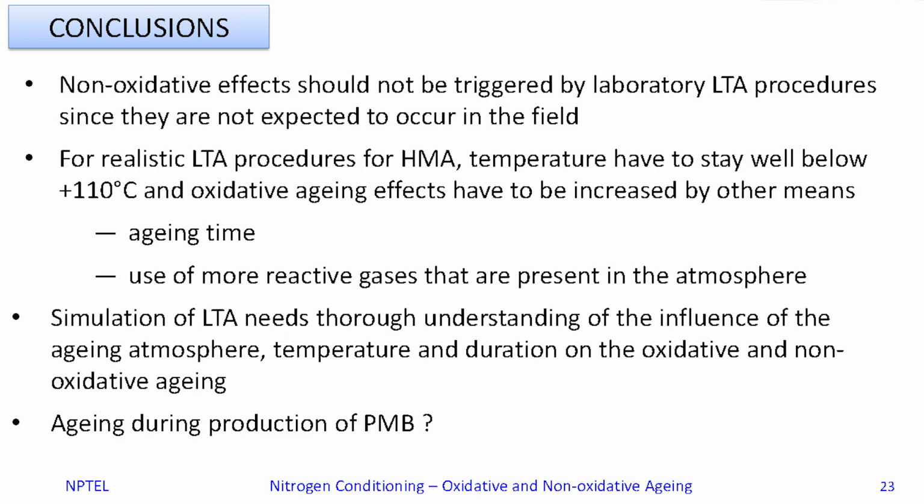The oxidative effect can be increased by other methods, by increasing the aging time or by the use of more reactive gases present in the atmosphere. And simulation of long-term aging needs a thorough understanding of the influence of the aging atmosphere, the temperature, and the duration on the oxidative and non-oxidative aging effects.